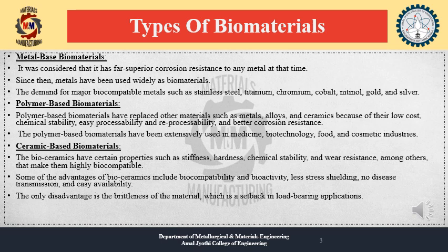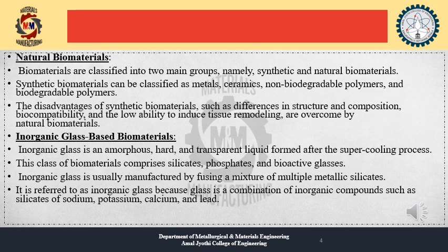The third type is the ceramic-based biomaterial. The bioceramic has certain properties such as stiffness, hardness, chemical stability, and resistance, among others, that make them highly biocompatible. Some of the advantages of the bioceramic include biocompatibility and bioactivity, less stress shielding, no disease transmission, and easy availability. The only disadvantage is the brittleness of the material, which is a setback in load-bearing application.